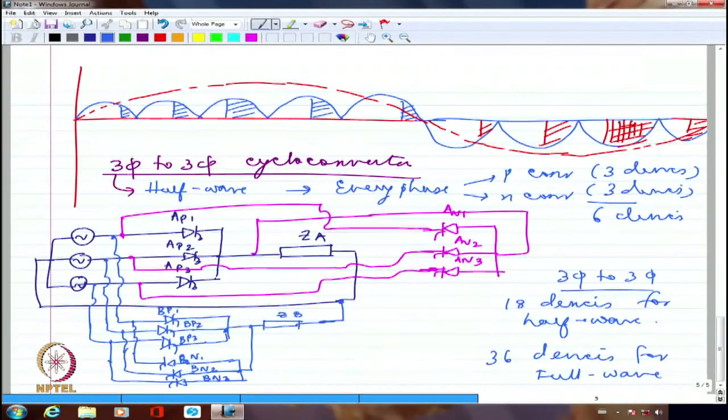Okay. So we have seen only single phase and 3-phase AC voltage controllers, where frequency will be a constant and magnitudes could be changed. RMS value of magnitudes could be changed. But the major problem is non-sinusoidal output.